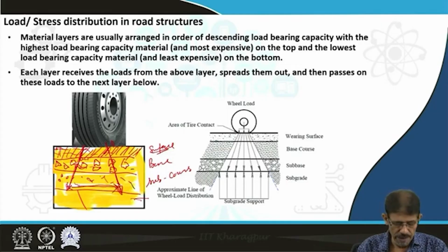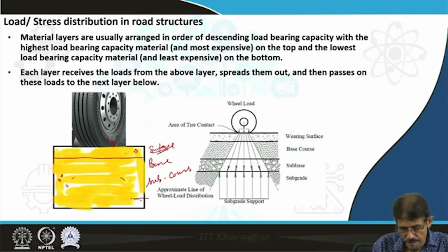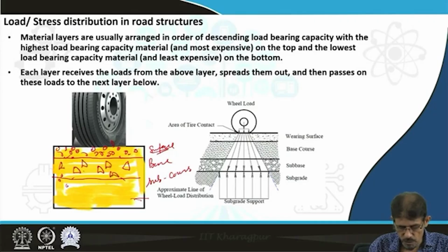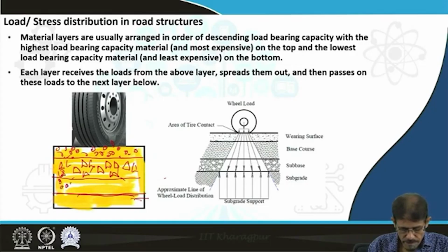However, in the case of flexible pavement, here I try to show the different layers present in a flexible support, like here the surface course made up of concrete consisting of aggregate and asphalt. Then the base course made up of angular type of aggregates belonging to crushed stone. Then sometimes, if required, we put one sub-base course made up of some stone aggregate, finer aggregates along with soil and sands, and this is the subgrade, sub-base course, base course and surface course.